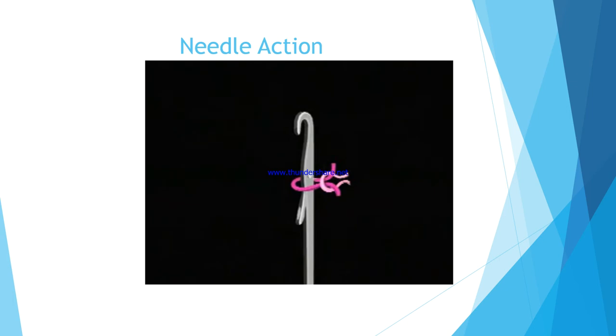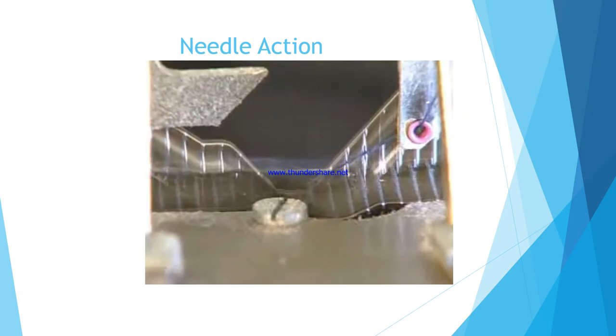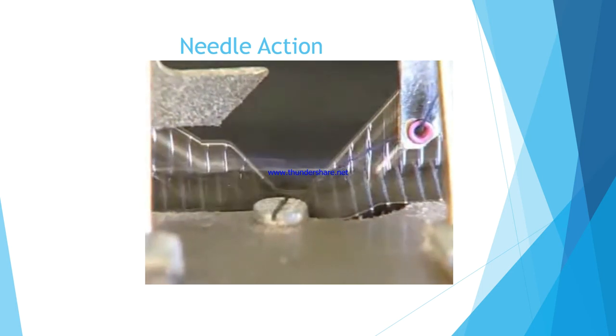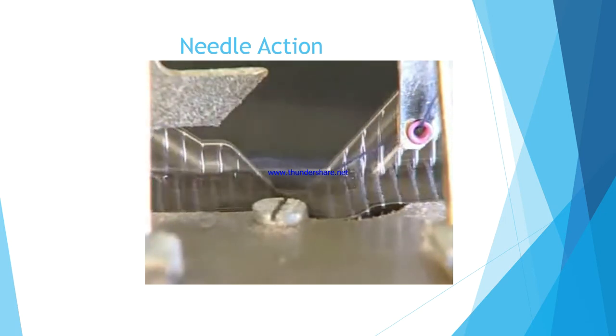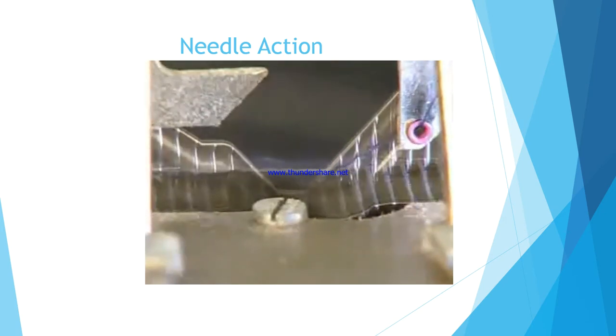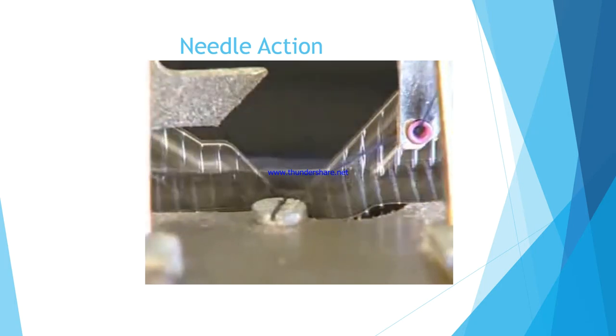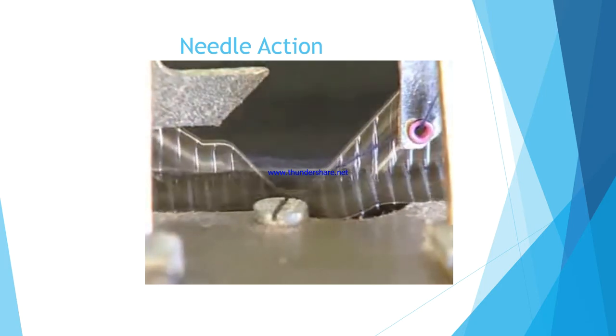The amount of yarn used to form a new stitch determines the stitch length. This is important because stitch length affects the weight, width, and aesthetics of the fabric. On modern-day knitting machines, needles make millions of loops or stitches a day. Needles may need to be replaced due to wear, but they usually last up to 6 months, depending on construction, yarn type, fiber type, and speed.